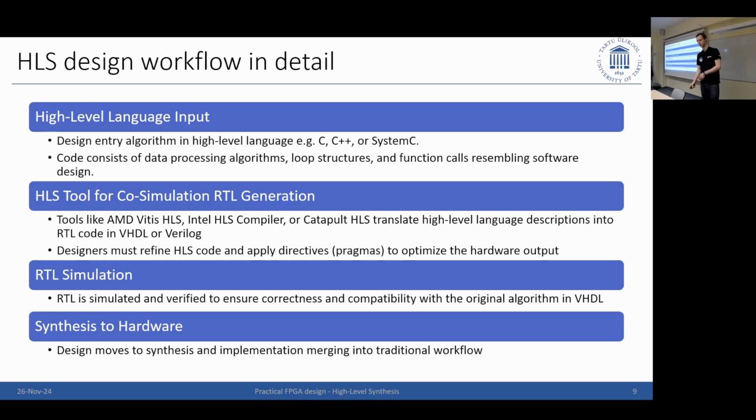And that's basically in the assignment. In the seminar, I will show you that, and probably we will do it in the assignment as well. You export the IP core from your HLS tool, and you load it into Vivado as a normal IP core, and then you work with it. Sometimes you just have to connect everything with the pins, but maybe you want to add the UART or Ethernet interface into your design, and then we have everything working together. I will give you a short example in the seminar for this, so you can see that a bit.